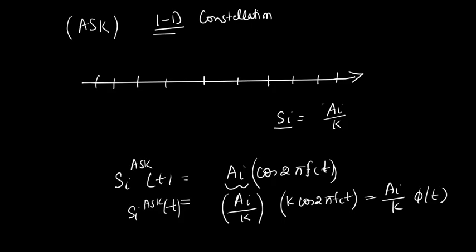Now, your aim is to write each of these in terms of basis. So, there is only one basis cos, just you need to normalize it. So, I have used a factor k, so that this becomes unit norm. You understood my point? Yes, sir. But why do we need to normalize it? Because of the very definition of the orthonormal basis, that all the bases must have unit energy, and the constellation points are always plotted with respect to basis. It makes analysis easy. For example, when this happens, then you can say that energy of each point, each waveform is the distance square.